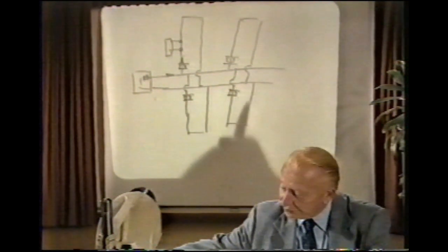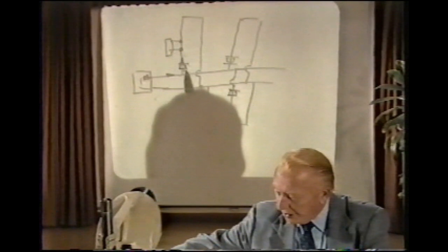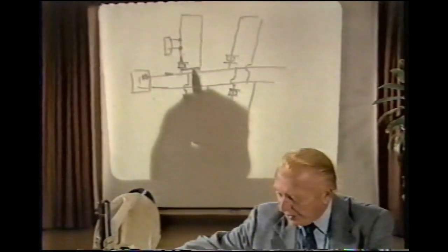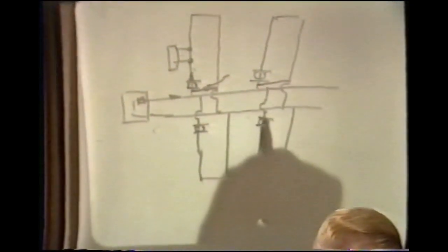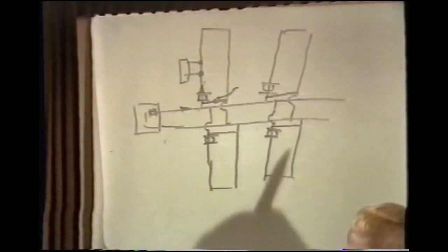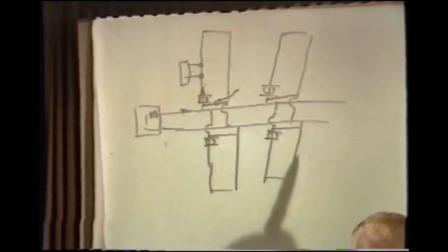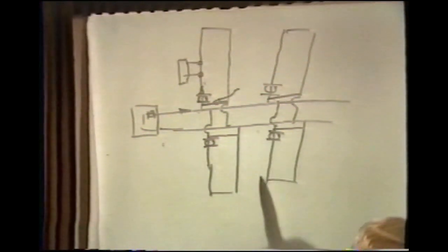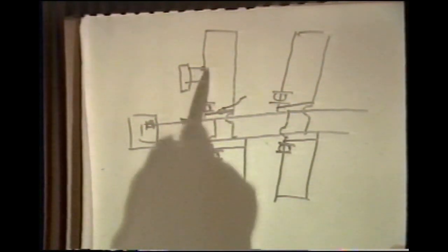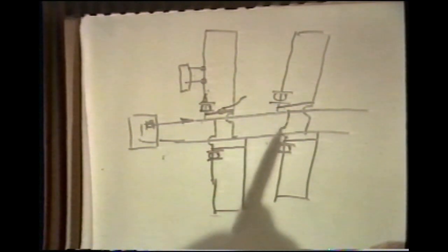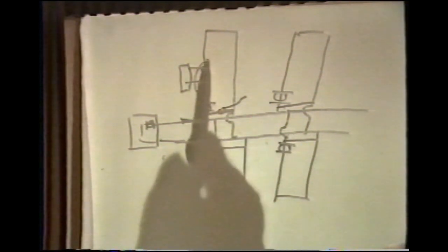It finally developed that our solution was this: to take each of the takeoffs into the secondary circuit and provide a section of pipe that we called common pipe. And with that common pipe, we were then able to disassociate the pumping of the building circuits from the pumping of the primary circuit. We then added pumps to each of the buildings, and because of the addition of the pumps, we were able to provide the necessary flow rate through that secondary circuit in order to establish the proper flow to allow the monoflow fittings to operate properly.